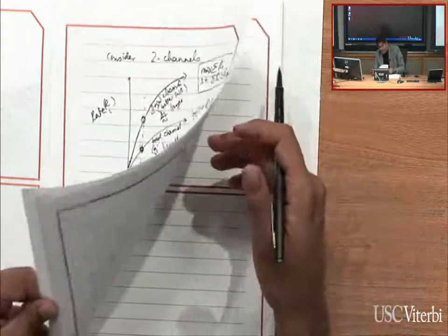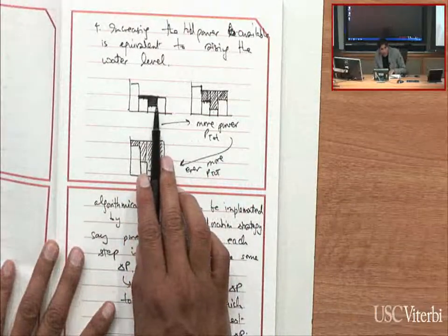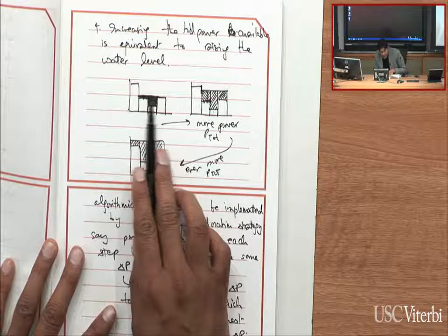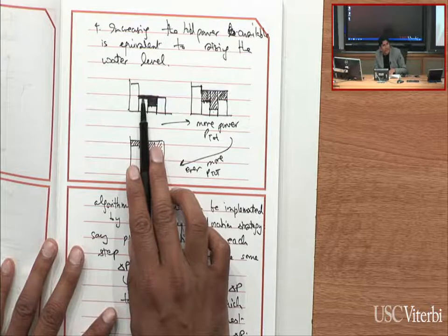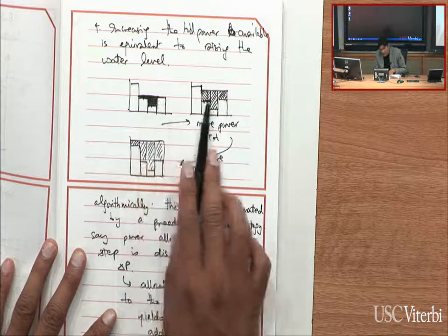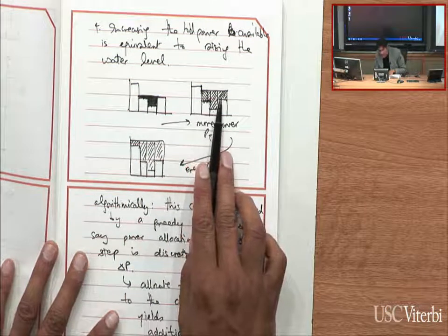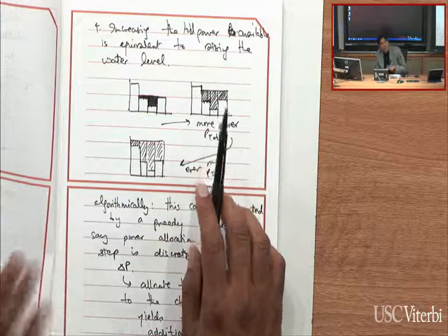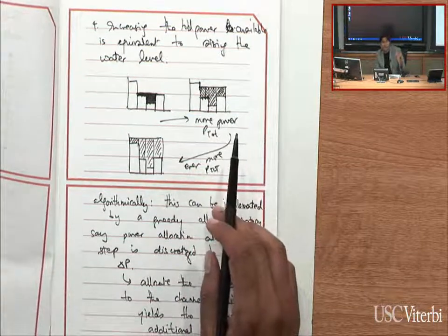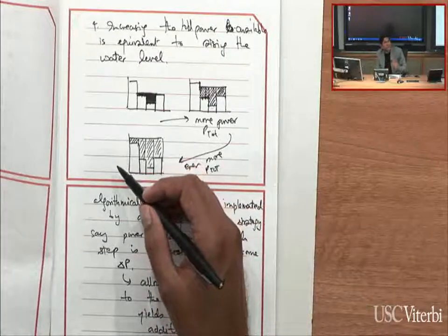And if you look visually at what the solution was doing, it has that flavor. The first unit of power I would have put into this good channel. I would keep doing this up to a point, right? Then there's going to come a point when I'm actually willing to invest some power in the second best channel. Okay? And of course, both of these will keep pace with each other. Then at some point, because of that water level being the same, we even start putting some power into the third best channel, because the additional return we get on that investment starts to be better in that third channel as well. And then for a while, we keep doing that for 3 channels. And then eventually, even the fourth channel starts to give us some return on the investment.